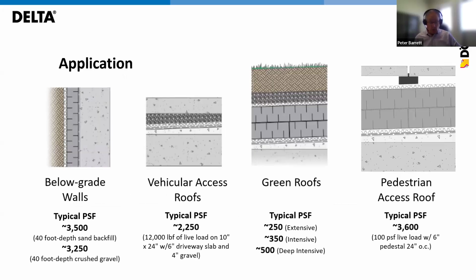So let's look at some of the real world pressures that you will encounter in various applications. When considering whether the drain board is suitable for applications such as an underground wall, tunnel, a caisson, pile and lagging wall drainage, retaining walls, bridge abutments, or as a relief layer for hydrostatic pressure on any substructure, you should consider whether it can also function as a protection board. Most waterproofing does require a protection board of some sort.